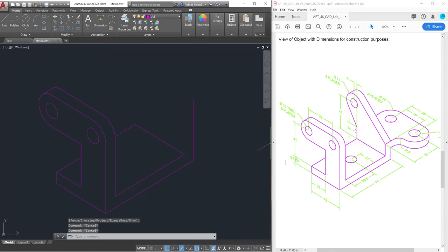And so next thing I want to do is maybe draw this line. So I'll go ahead and draw this line upwards, a distance of 14 millimeters. That also is the height of this one here, so I can go ahead and draw that upwards 14 as well. And then move it back this way, some arbitrary amount for now, and maybe even copy this down a distance of 8, and then clean up this point here and this point here.